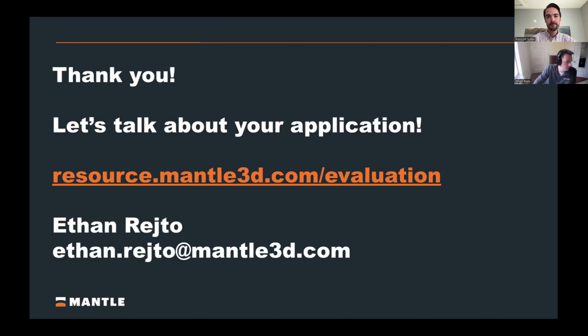Awesome. Another question here: when we're nesting parts on the build plate, can you print dissimilar parts? We showed a lot of examples of the same part being printed multiple times. What if I wanted to print five different core geometries? Yeah, absolutely. Certainly possible. A number of our customers are doing just that. So the simple answer is yes, absolutely. We'd encourage it. I think our one guideline is if parts are very dissimilar in height, it's not that you can't do it, just that you're losing some of that value, because you could have turned over the whole build, since you're going to be waiting just for one part to be completed.